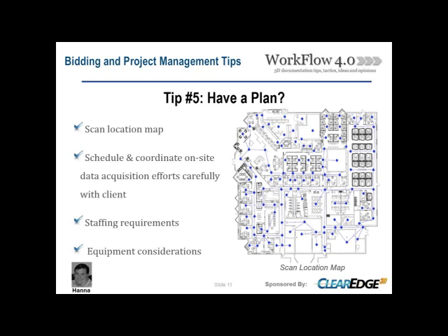Consider your staffing requirements. Are you dealing with this with one scan crew, 2, 3, 4? How are you going to do that? Getting it staffed properly. And furthermore, collecting the data is only one aspect of it. You're going to have a lot of data to register and clean up. That takes a lot of resources, so make sure you have all those resources and capabilities at your disposal to support you. And then lastly, equipment considerations. Whether you own it or you're going to rent it, make sure you're going to have those resources in place with all the accessories, targeting spheres. So those are all really important items to consider.